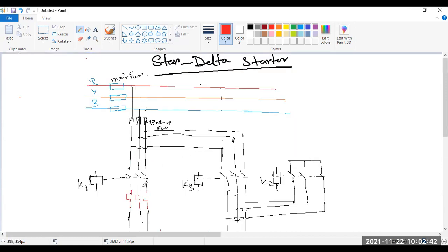And this is your overload relay. From this symbol you have to understand, because in your panel diagram there are no such statements. There are some labels like K1, K2, FB, OLR, and somewhere there are not even alphabetic words, just symbols. So through the symbol you have to understand which one is an overload relay or overload circuit breaker.